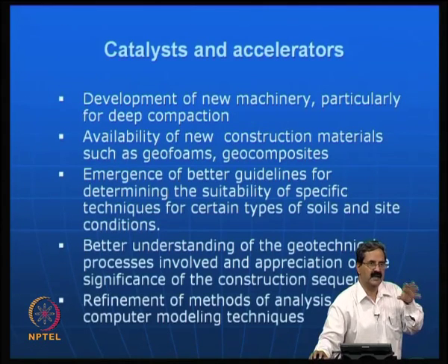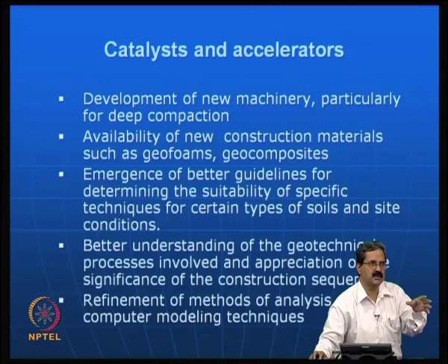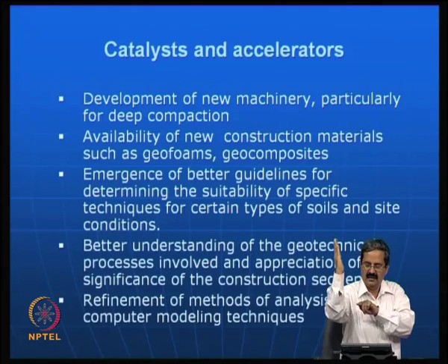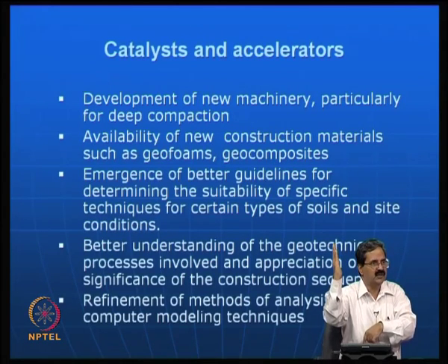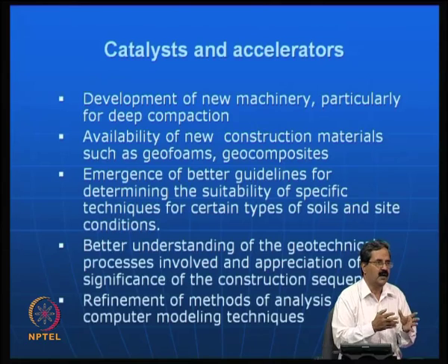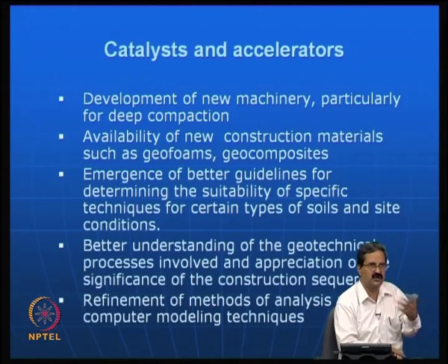Even in the creation of tunnels, you excavate something, then you shotcrete, then you put some reinforcement. There are some issues in tunneling also. Many of these geotechnical problems are more about construction sequence. C and phi and other engineering parameters will give you some information, but if you want to really understand the deformation, say there is a tall structure and I want to excavate next to it, I should excavate just 1 meter, then calculate the factor of safety and the deformation. Then go for the next 1 meter, and calculate the factor of safety and deformation again, sequentially, putting in reinforcement or a sheet pile wall, many things could be done. If you are doing a sheet pile wall or some micro piling, the micro piles have to be put first and then the excavation should be done.